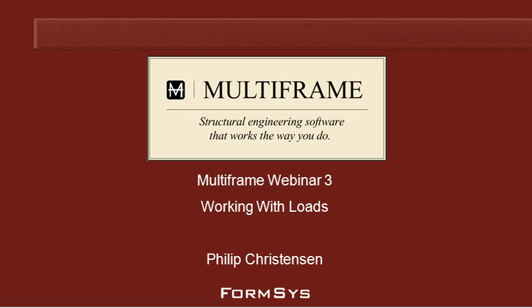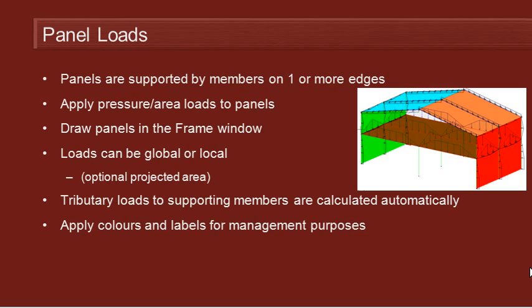Hello and welcome to Multiframe Webinar 3 Video 4 on working with loads. Moving on from joint and member loads, let's now take a look at how we can apply loads to areas and then automatically do tributary area calculations for the members around the edges of those areas.